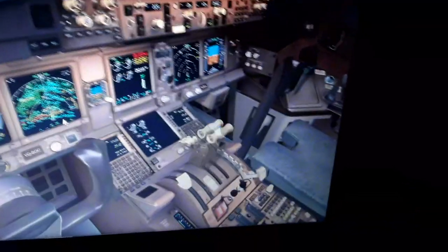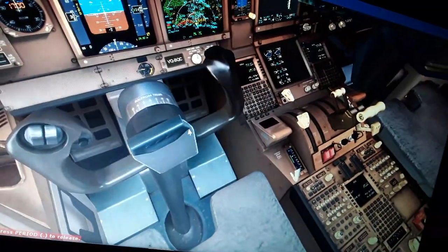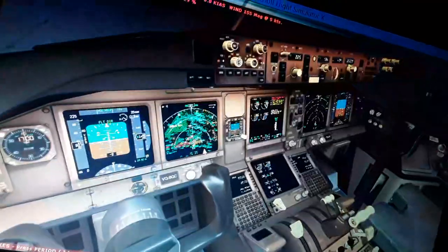We have the action and reaction by moving the aircraft forward using the expansion of the accelerated gases from the turbine, the left and right turbofan engines. Which makes the aircraft just move forward, not upwards into the sky. It can only accelerate forward with the engine. So you use the thrust levers to accelerate the aircraft, and then you need to pitch up with the elevator.